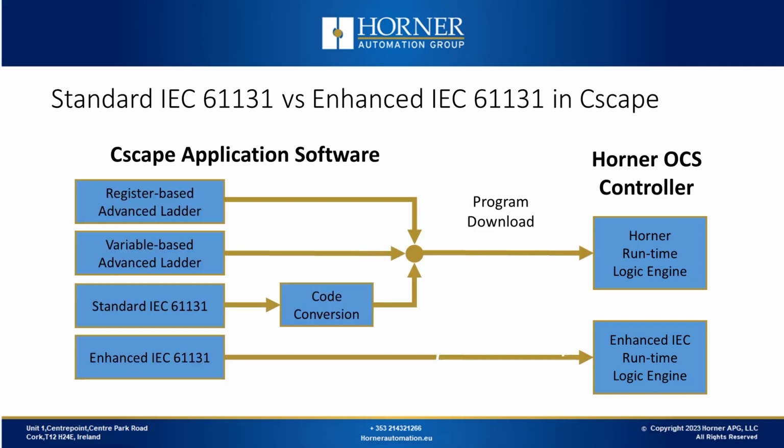Now we'll look at the technical details. The three original languages, register-based advanced ladder, variable-based advanced ladder, and standard IEC, all execute from the Horner runtime engine. However, the standard IEC requires a code conversion in Cscape before download, as it can't run directly on the Horner logic engine.